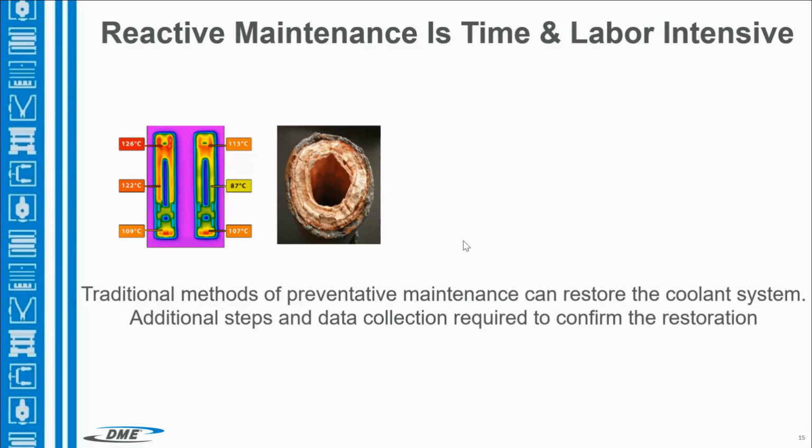And right now we're looking at cooling. We were able to track our coolant circuits, and we were able to see when we were trending out of our control limits that, hey, we have water channels that are becoming blocked. They're not transferring heat at the same rate. They have a higher pressure drop, and we need to get that tool out and take care of it. And we could plan that in versus being reactive.